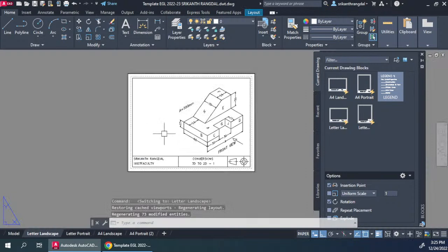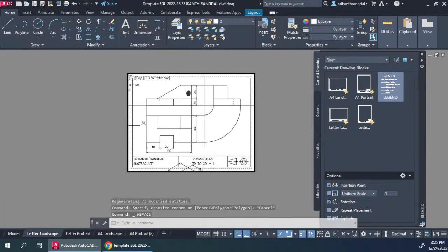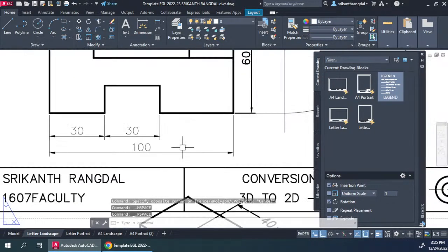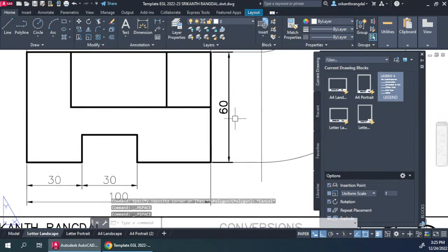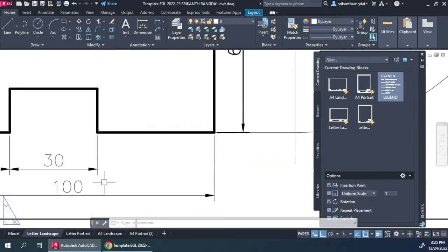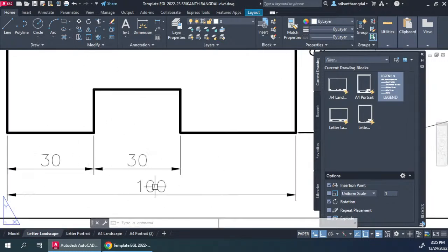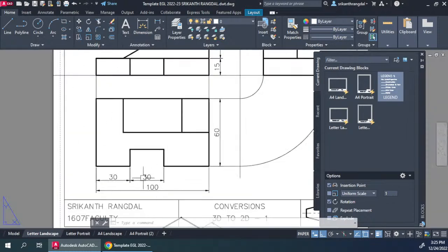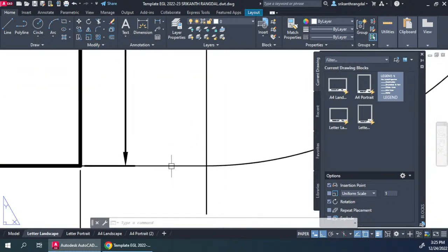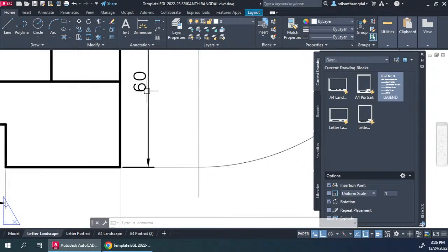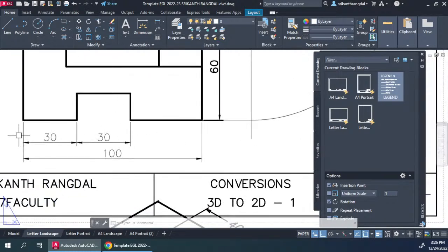So when we go in here, double click inside, and when we are adjusting this diagram here, fine, so double click outside. Then when we zoom in here, you can see that these dimension lines where we had applied the dimension properties are appearing thicker, and compared to these, the other dimension lines are still very, very thin. Okay, so that has to be a difference. There has to be some difference between the construction lines, the projector lines, which have to be the thinnest possible thickness, and dimension lines are medium. They should have medium thickness, and that's the thickness which is allotted over there.